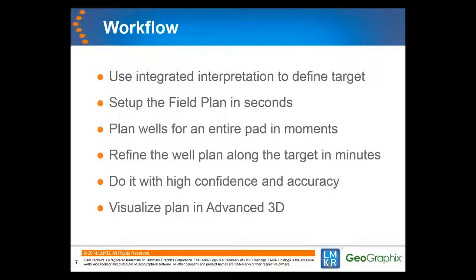LMKR Well Planner will then be used to redefine and define the wells in the plan into an accurate drill-ready design based upon drilling parameters like approach and lateral dogleg severity and drilling geometry algorithm. Finally, the field plan will be visualized in the new Pro 3D visualization application along with isomap surfaces, depth-converted seismic sections and slices, and fence diagrams with interpolated reservoir attributes.